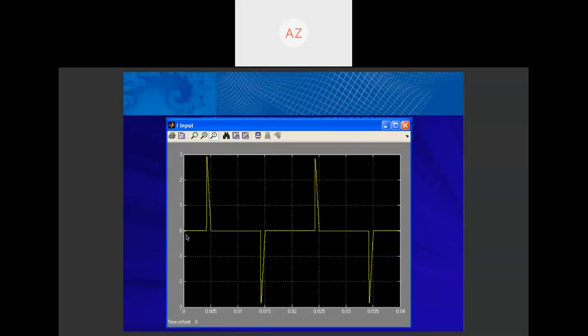And it will appear, this is the supply current waveform. This is the distorted supply current waveform in time domain. From this waveform, we know that this distorted supply current waveform is rich of harmonics, which could lead to a high total harmonic distortion level. So now how to do analysis on this waveform, I mean the supply current waveform?